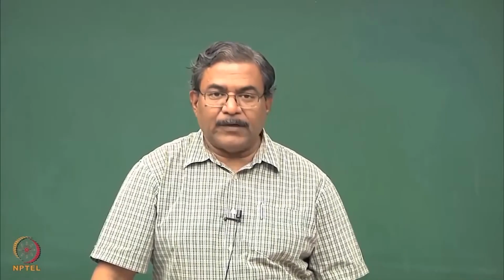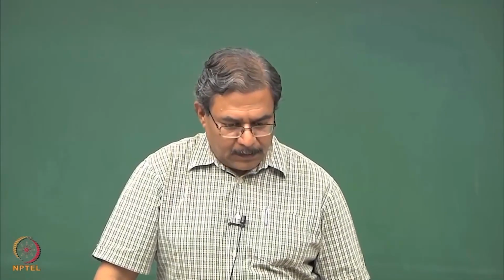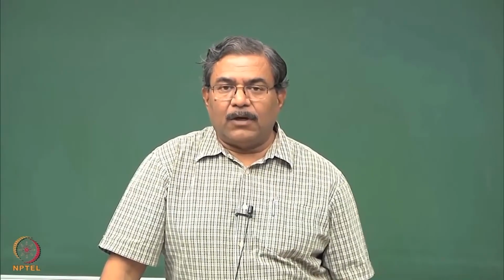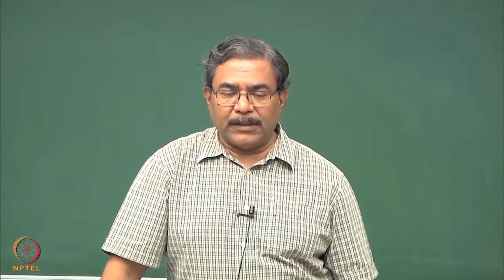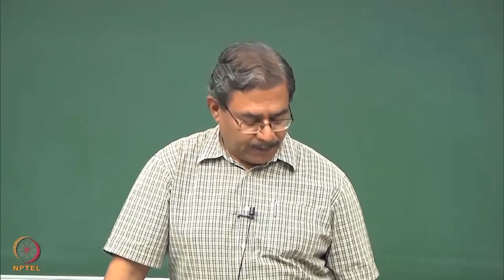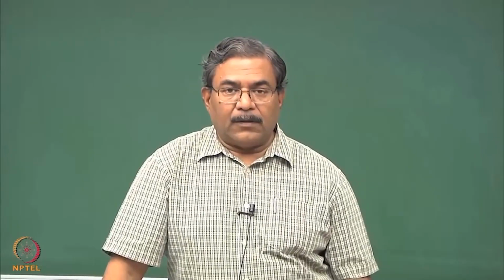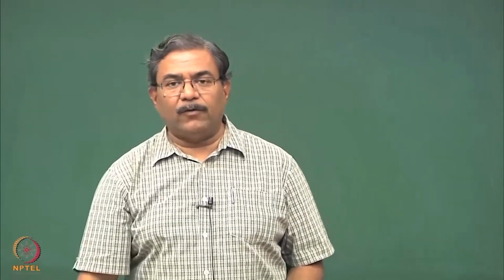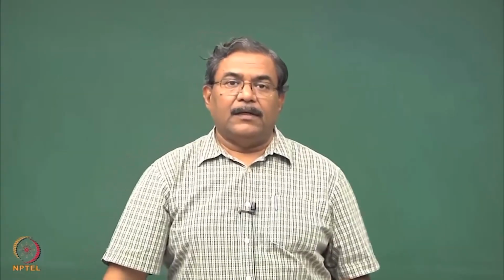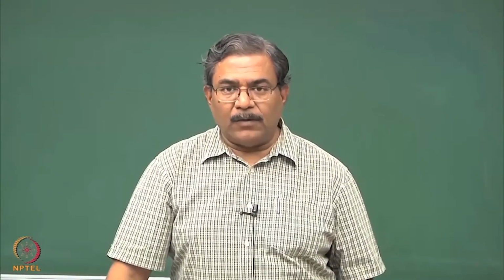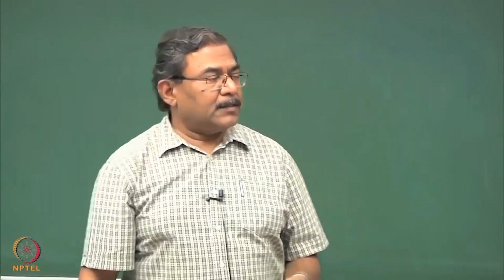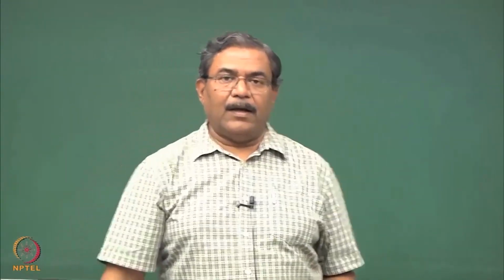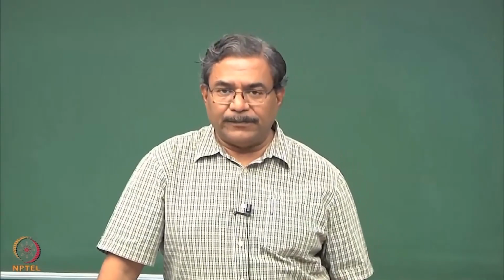Welcome to lecture number 23. What we have realized is that once you solve the one dimensional consolidation equation proposed by Terzaghi, the coefficient CV, which we have defined as the coefficient of consolidation, remains unknown, and hence we have to conduct experiments to obtain its value.